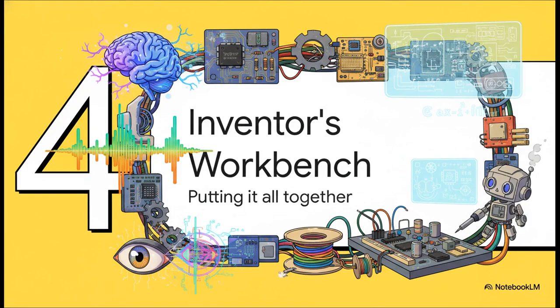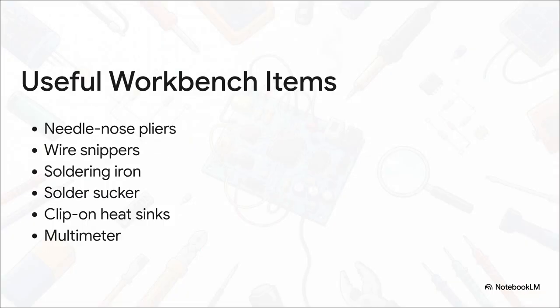And that brings us to our final stop, Section 4, the inventor's workbench. It's time to start putting it all together. So the absolute crucial point here is, you just can't build great electronics without having the right physical tools. Our source material gives us a pretty definitive, no-nonsense checklist for a proper setup. Beyond the obvious stuff like a good soldering iron and a reliable multimeter, you are absolutely going to need precision needle-nose pliers and sharp wire snippers. You'll definitely want a solder sucker to fix your inevitable mistakes, trust me on that one, some solvents for cleaning things up, and clip-on heat sinks. Those are lifesavers for protecting your delicate active components from burning up while you're trying to solder them into place.